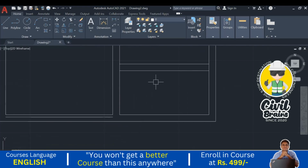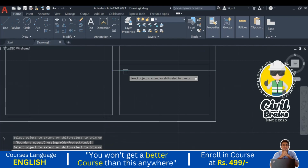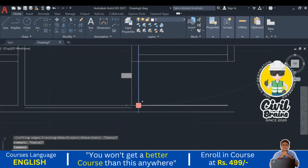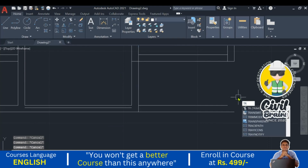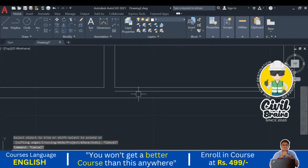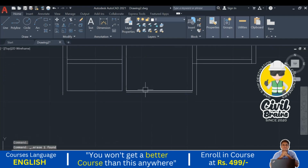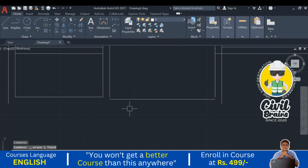To trim that, you first extend this portion. Here you extend, and here also you extend, and for the remaining portion you go to the trim command and trim this one. I extend this one also, otherwise it will be a little difficult while trimming. Here we can consider this as our wall. This I just delete. This is our inner wall now, and offset 0.23. Enter. This is our external wall.